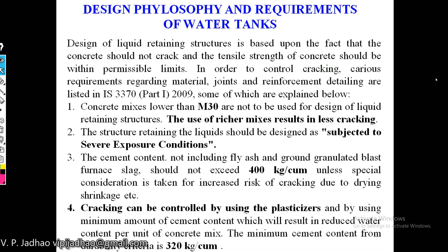Now what is the design philosophy for design of water tank? The concrete for water tank should not undergo any type of crack, and the tensile strength of concrete should be within permissible limit, because we don't want any cracks in the water tank, as cracks will lead to leakage.